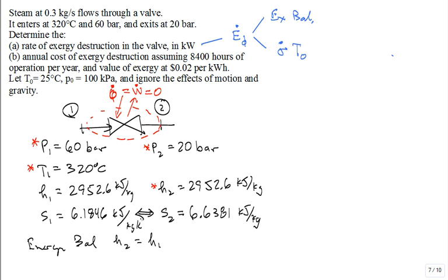Sure. Let's do our entropy balance. Our second law, what does it say? Well, I'm running out of room, so I'm just going to read it out loud. I have some incoming entropy with the mass. And then I'll have some entropy generation per mass flow rate through it. And all of that has to be taken out. There's no way it can go out with heat transfer. It has to go out with the outgoing mass transfer. So S2 takes it away. S2 is greater than S1. By how much? By the amount of irreversibilities that generated the entropy.